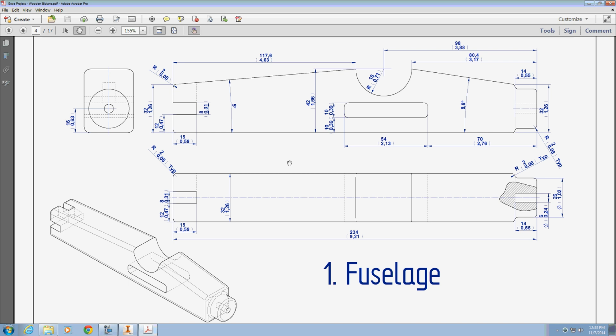And for this part, we're going to model the side view here, and then extrude it to its thickness, and then add the details such as the fillets and the nose piece here. For the very front here, we'll just model this squared off, and then we'll cut away at the round portion to make the nose piece here. So I'm going to basically draw this sketch right here first. There are a couple of extraneous dimensions there we don't want to add, but I'm going to start by drawing the basic shape and then coming back and adding some dimensions.